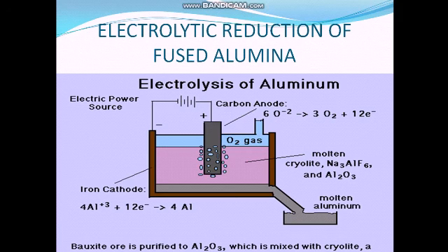Now, we will take the temperature of 950 degrees Celsius for heating the electrolyte, and 5 to 6 volts of voltage should be provided to melt the electrolyte. When this temperature is provided, cryolite, fluorspar and alumina will decompose to form positively and negatively charged ions. The positive ions present in the solution are sodium, calcium and aluminium ions, while the negative ions formed are fluoride and oxide ions.